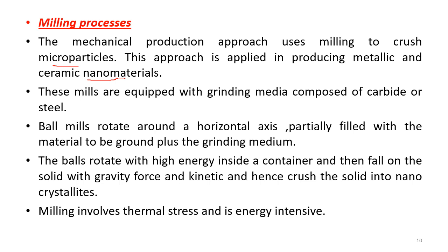Here the grinding media is composed of a carbide tip, or case hardened steel. The steel balls are going to be rotated. These steel balls rotate around a horizontal axis. They work in an inert gas medium, so that the particles don't get oxidized and are free from contamination.